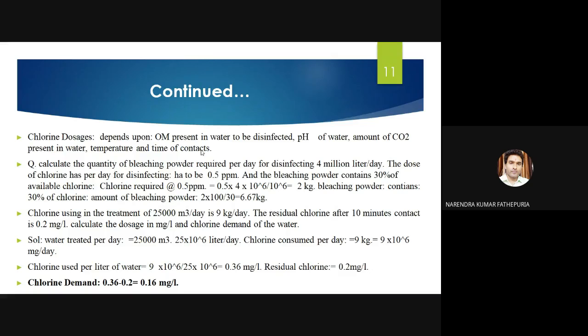What should be the time duration for the chlorine doses? 5 minutes, 10 minutes, 20 minutes, 30 minutes, that we have to decide. And temperature also plays a very important role while we decide the chlorine doses. Suppose there is one question they are asking for the chlorine demand.